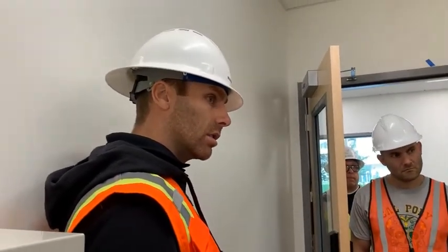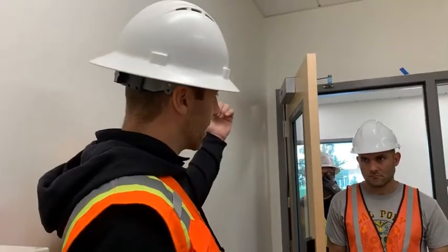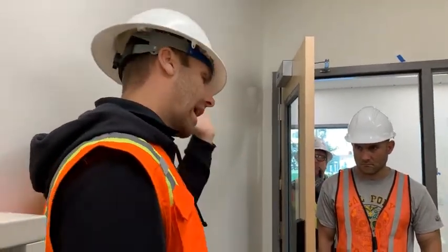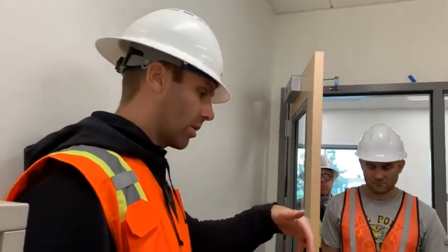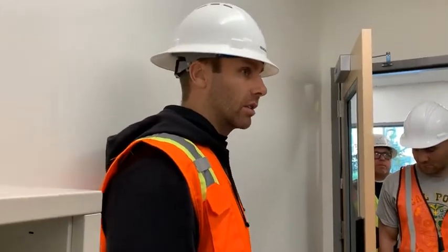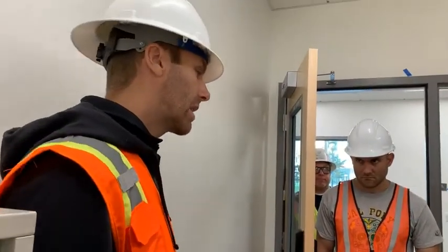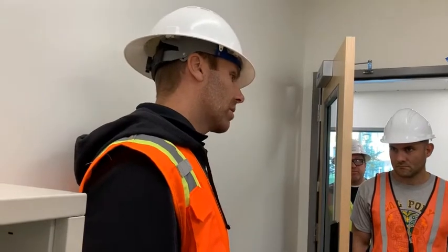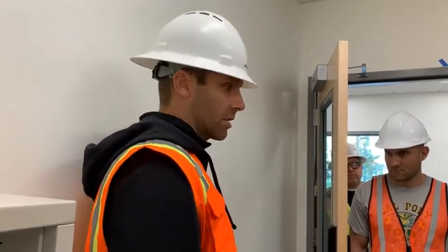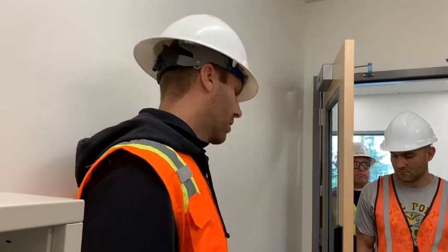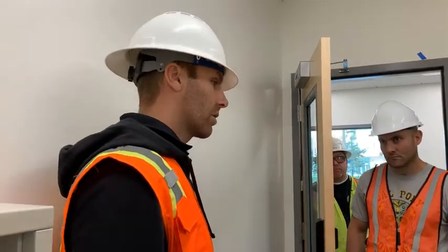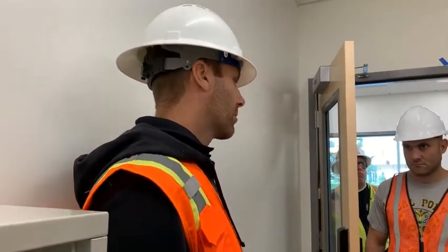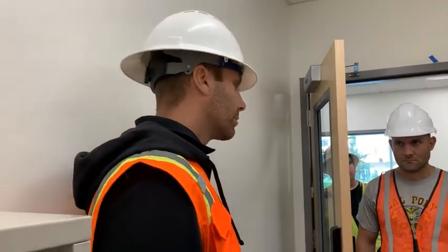And these are just in office areas and stuff. Typically, office areas, you probably have it in the receptionist area. You're not going to have it in the rooms or anything like that. It's not required. Areas like an electrical room, stuff like that, if you even have a receptacle, it's not going to be controlled. Title 24 thing? Yeah, exactly. Title 24 dictates you don't always have to do it, but when it comes to new construction, it's mandatory. There's some ways to get around it if it's not new construction, but new construction is always now, and it always has been in the last 4 years now.